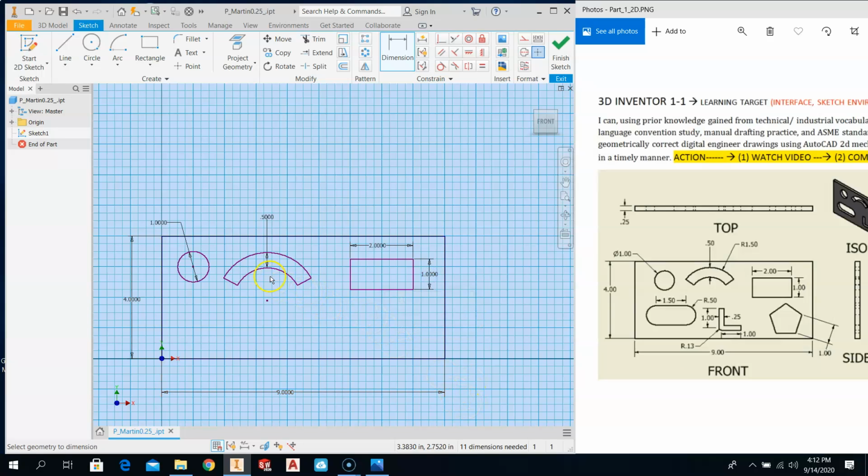There we go. Okay. One thing I missed here, kind of on purpose, is this radius of 1.5. So I'm in dimensioning mode here. And if you look, it's 1.5818, isn't it? So now I can change this to 1.5. So I thought that was 1.5. That was not a teachable moment. I thought that, but see, I just double checked it by dimensioning it. And now I've got it the correct dimension. And again, use this as a dimensioning guide. So they do a pretty good job on here. We're not being real picky right now.